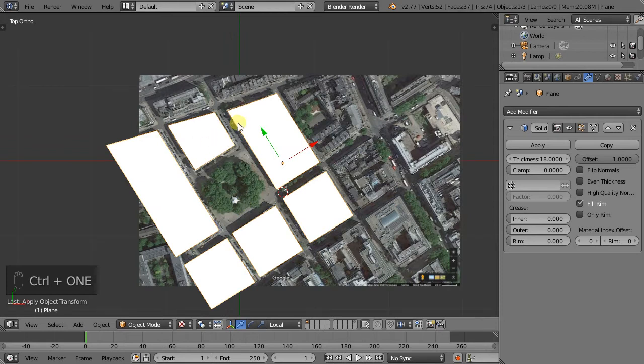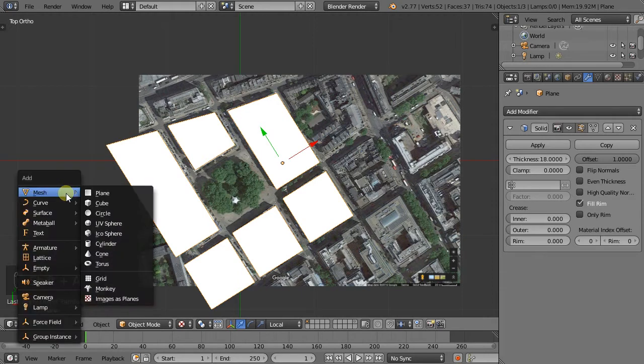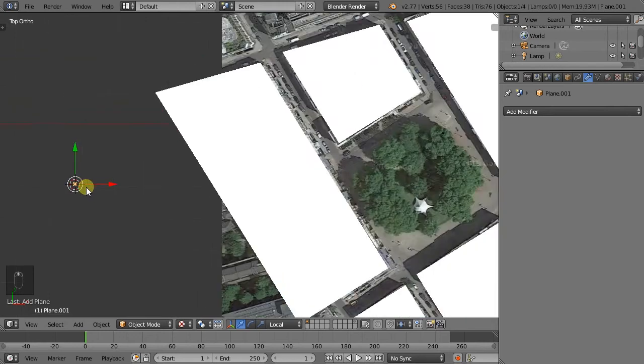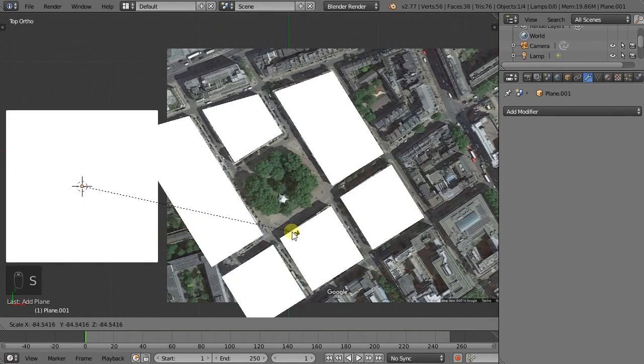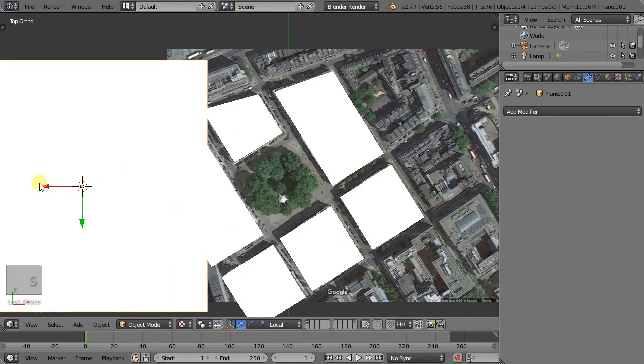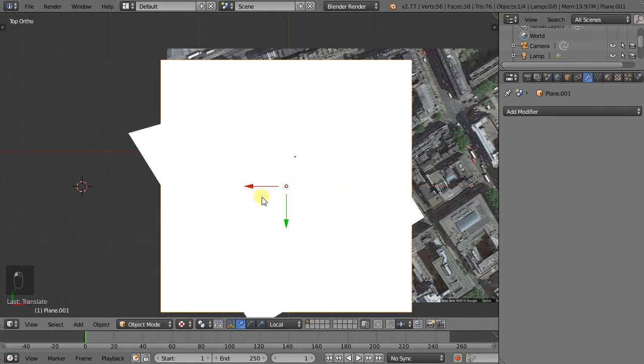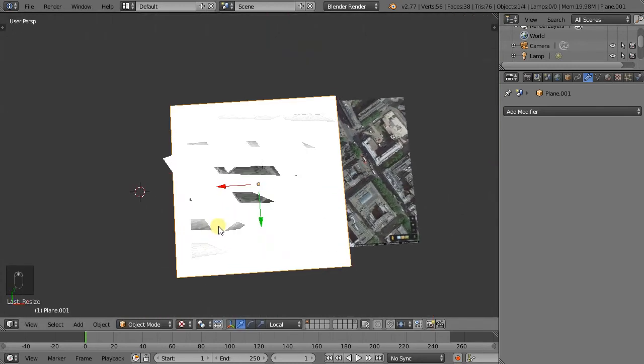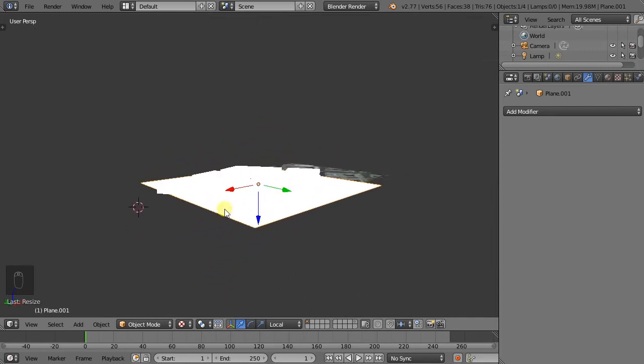So if I go to top view, the next thing I would like to add is the road. So if I click, let's say here, Shift A, Mesh, Plane. It's quite small, that's why we can't see it. Scale. Something around this is good. Maybe just a little bit more with S. And it's getting a little bit hard to see.